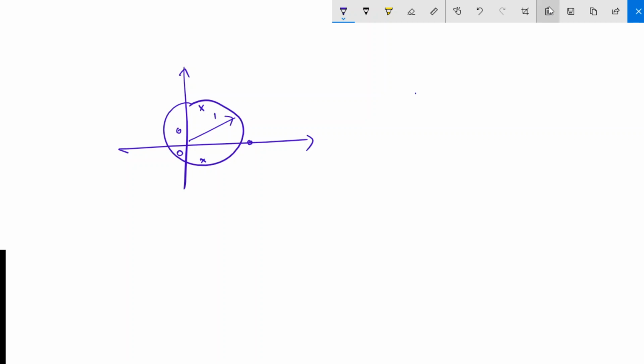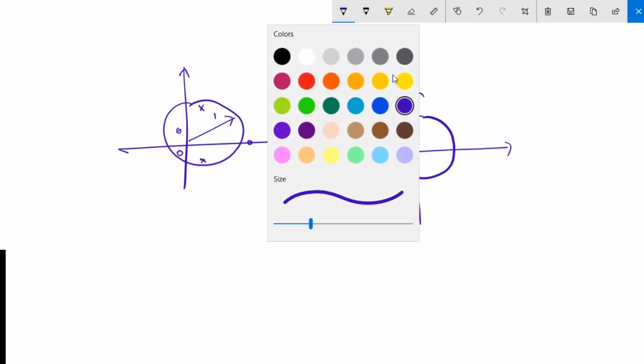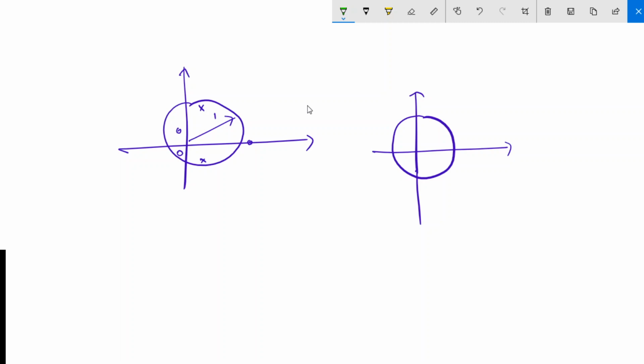Suppose you have designed a filter or a discrete time system in which one pole may be lying very close to the unit circle, maybe at a radius of 0.99. Right now, since this pole is inside the circle, your system is stable.